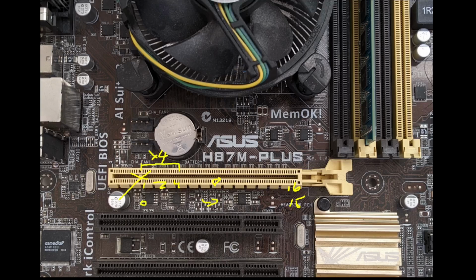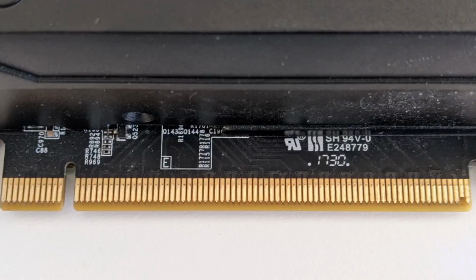When such a card is inserted into a normal motherboard, PCIe initialization does not work at all. This is because lane 0 on the GPU is dead, which means that none of the other lanes can start up, and the PCIe device cannot actually negotiate even an X1 connection. Usually measured with a multimeter in diode mode, you can get an open line reading or abnormal values compared to other lanes when you are probing the pins.